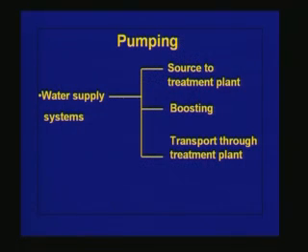So, the pumping is also required to boost up pressures in water distribution networks in certain cases. We also need pumping in water distribution networks to transport water through treatment plants, because a lot of energy loss occurs in the treatment plant piping.